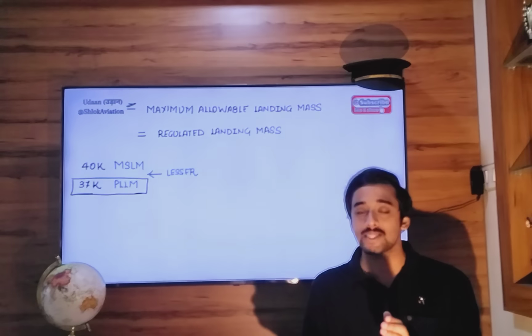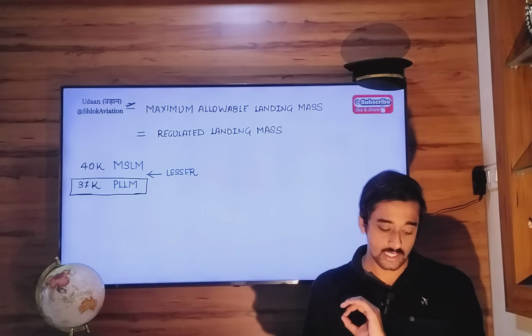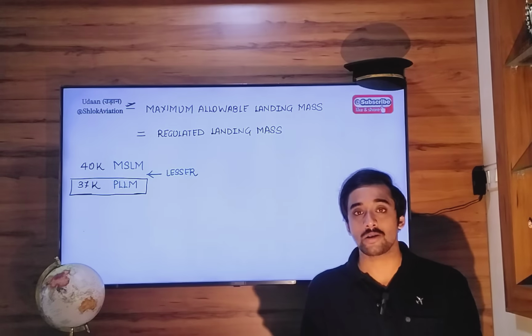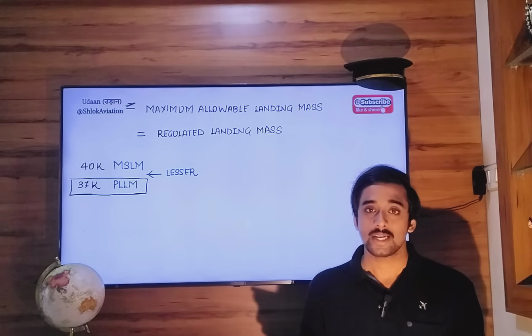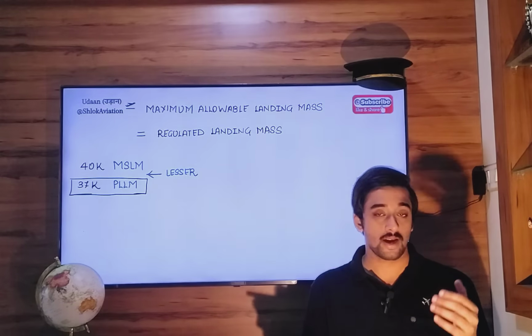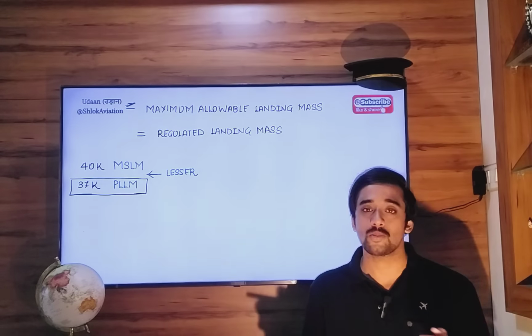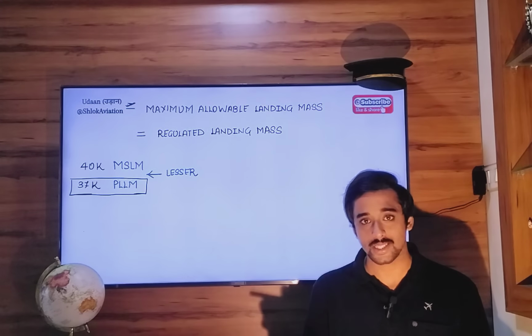Always choose the lesser value. Even when deciding a regulated takeoff mass, you are going to select the lower of maximum structural takeoff mass and performance limited takeoff mass.